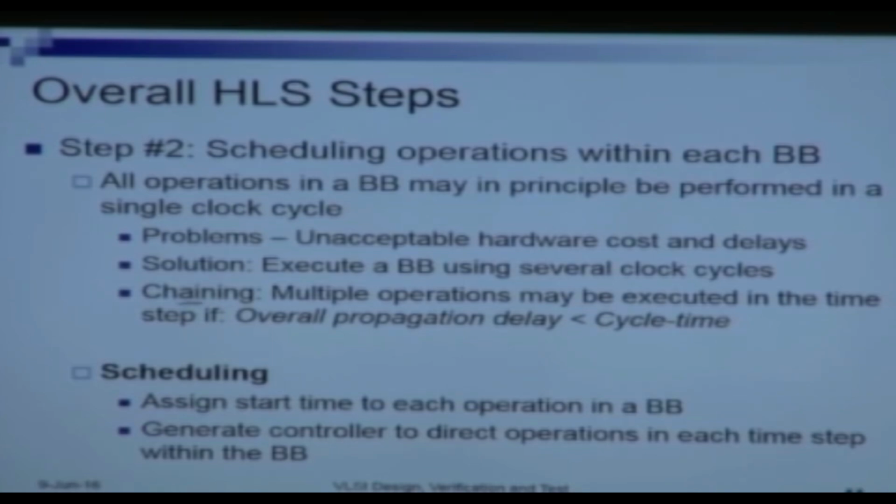So what is chaining? Multiple operations may be executed in the same clock step if the overall propagation delay of all these operations together is less than a clock cycle time. So therefore, this only complicates the scheduling problem itself.